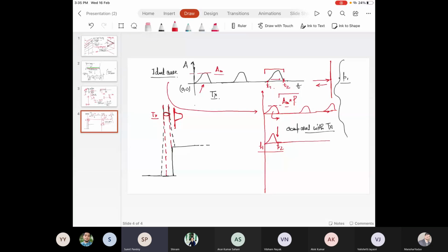Sir, that is due to diffraction. Correct. So how do we calculate the diffraction angle alpha? This is due to diffraction. So that is 2.44 lambda upon dt, where dt is the transmitter diameter. Correct. Though this is not a part of the discussion, in due course of the lecture, I will also take up the concepts which we have already discussed previously, so that there will be revision as well.